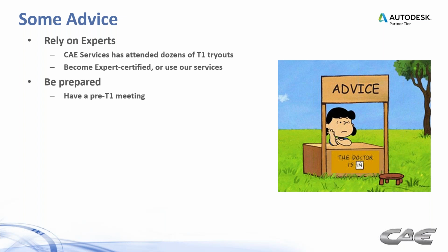So have a pre-T1 meeting. The mold shops and the part suppliers should all be aware of these standards to the extent that they know what they have to do and they know that it has to be done per GM's requirements. So have that meeting and discuss what's going to happen at the press so that when you get there, everybody's on the same page and you can get through it relatively quickly. If everything goes well, it really shouldn't take more than half a day to a day to get this done.